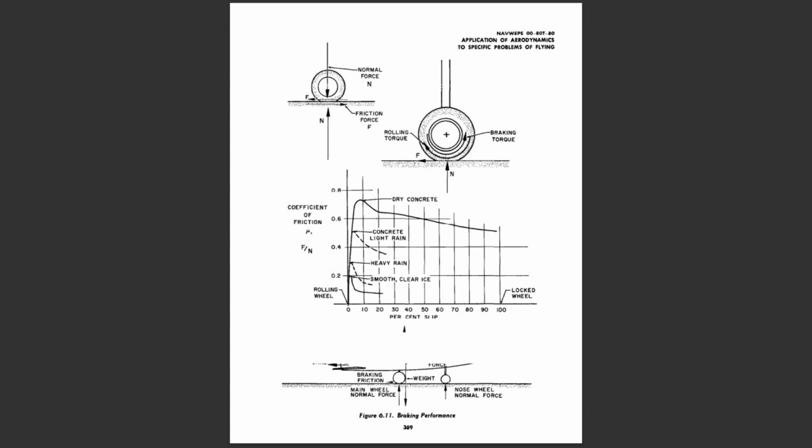Aerodynamic drag will be of importance only for the initial 20 to 30% of speed reduction from the point of touchdown. At speeds less than 60 to 70% of the landing speed, aerodynamic drag is of little consequence, and brakes will be the principal source of deceleration regardless of the runway surface. For the conditions of minimum landing distance, aerodynamic drag will be a principal source of deceleration only for the initial portion of landing roll for very high drag configurations on very poor runway conditions.